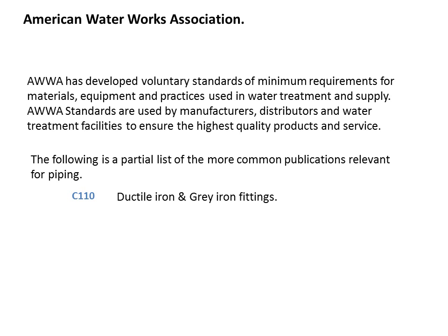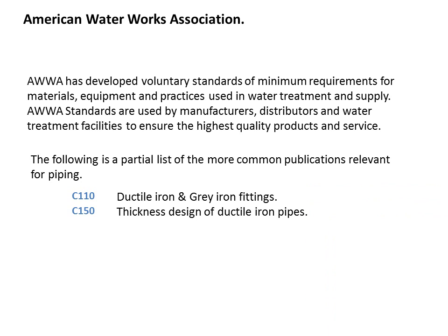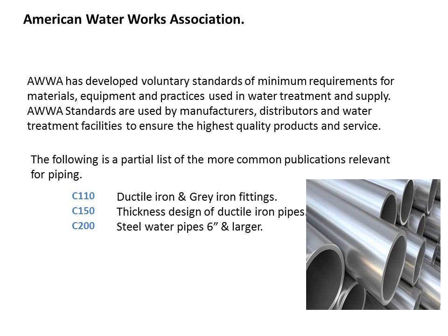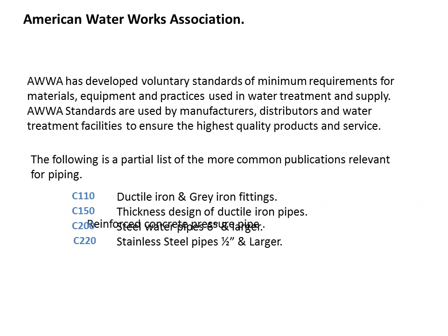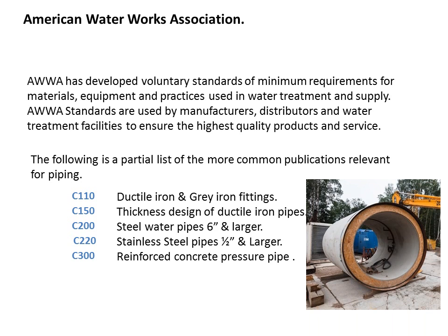Standard for ductile iron and gray iron fittings is C110. Standard for thickness design of ductile iron pipe is there in C150. Standards for steel water pipe 6 inches and larger are there in C200. For stainless steel pipes half inch and larger, we have C220. Standard for reinforced concrete pressure piping is contained in C300.